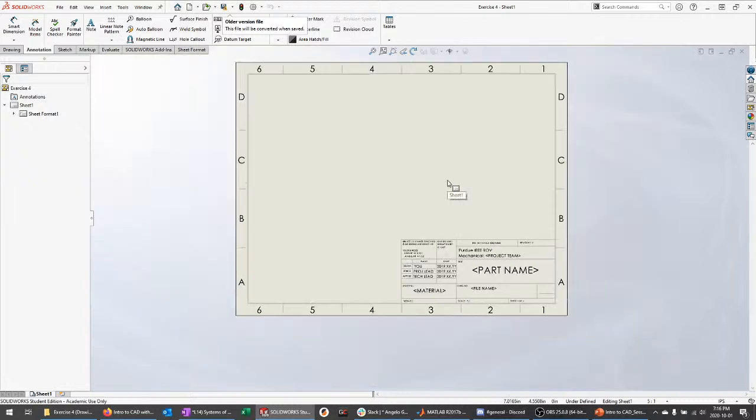That is actually one of the other uses for drawings beyond actually making engineering drawings. If you set up a drawing to be 8.5 by 11 and then create a view of a part at 1:1 scale and then print it out, then you can have a 1:1 printout of your part. And that's the sort of thing where you can use spray adhesive to attach that to a sheet of plywood or plastic or aluminum sheet stock, and then use that as a reference for a drill press or bandsaw or what have you. So there are other hackier uses for the drawing part, or rather drawing file type.